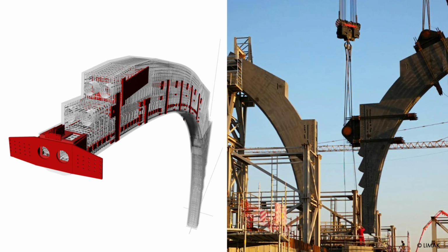Just the size and the complexity of it required developing solutions, and it was our role to make sure that there is a high control of every single component and a high level of precision in the fabrication, despite the time constraints and, of course, as it's a real project, the economical constraints. So out of a 3D model of all the different elements, the rebars have been modeled, and the embeds, which build the interface between the concrete and the shell cassette and the roofing. All of that has been integrated to make sure that there are no clashes, that the systems are working in terms of load-bearing capacity, that they are constructible. All of this has been checked and has been led down to the build condition.